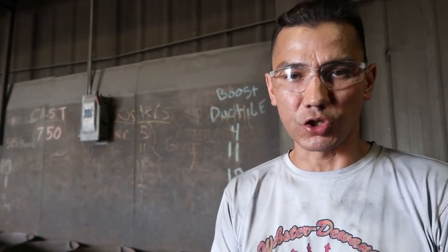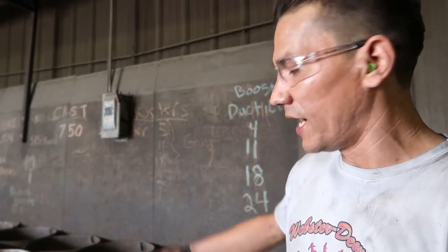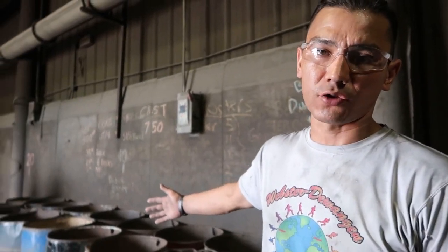This is where we make sure the right amount of weight, steel, cast iron, coke, rock, manganese, silica is all being added properly to be charged into our cupola here. We had 700 pounds of cast iron, 300 pounds of steel, 24 pounds of silica, 35 pounds of rock, along with 1 pound of manganese. And that's so we get the correct chemistry coming out.